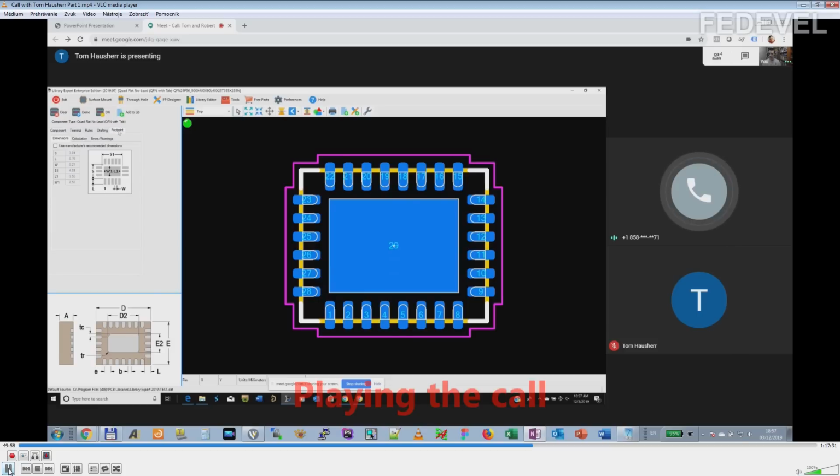thermal pad there. Now for the manufacturer footprint here, I know what Analog Devices and Linear Technology do all the time for their recommended patterns. For these QFNs, IPC calculates a 3 millimeter spacing in between the pads, but Linear puts it at 3.2, on all their parts, and then 4.2 over here. Then they round this number down to 0.7 and down to 0.25 or whatever. They have all kinds of nice numbers, and they click OK, and this would be the manufacturer's recommended pattern for Linear Technology or Analog Devices. I would probably go with their recommendation because they make reference designs, so they've got to make a reference design of this part, and they've got to prove out the circuit somehow.